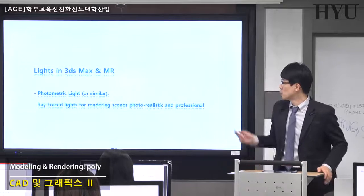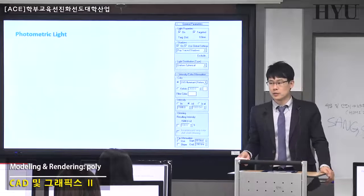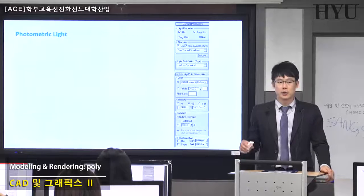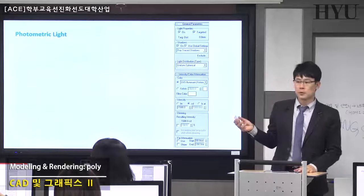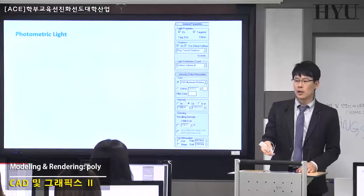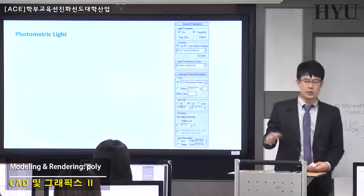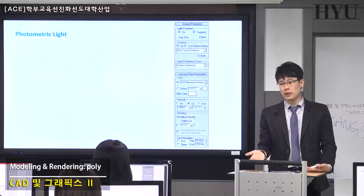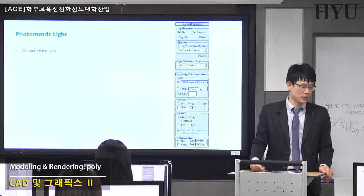The name of light is photometric light, okay? Photometric light is simply ray traced, very sophisticated and well-designed high-quality lighting system, okay? Photometric light, but only for Mental Ray, default renderer. If you are using V-Ray, you have to install V-Ray light, okay? Not photometric light or just standard light. Actually, standard light is okay in both V-Ray and Mental Ray, but photometric light is Mental Ray specific. That's why you are using photometric light today.